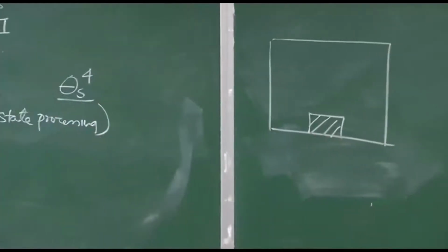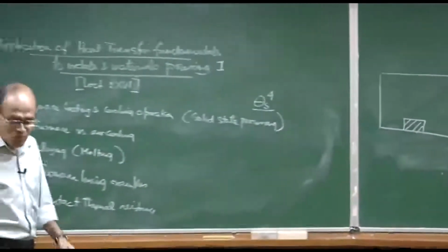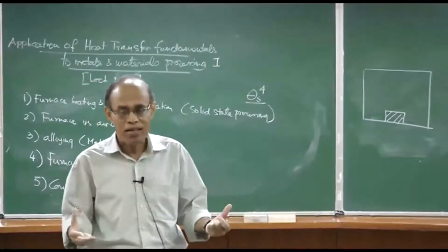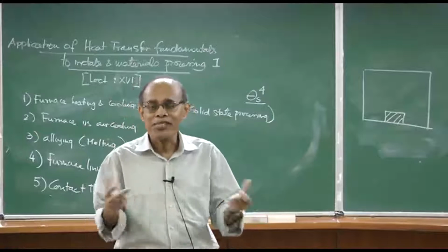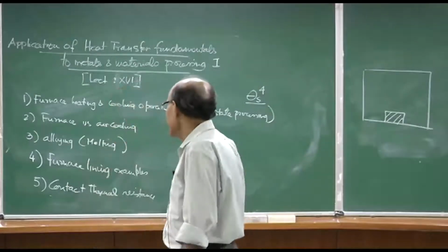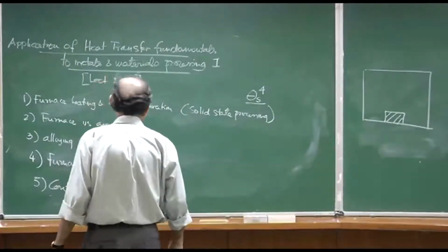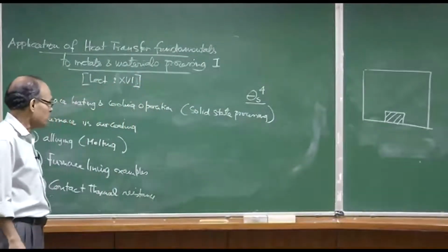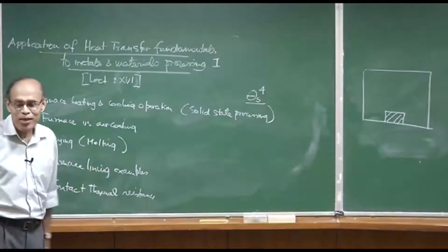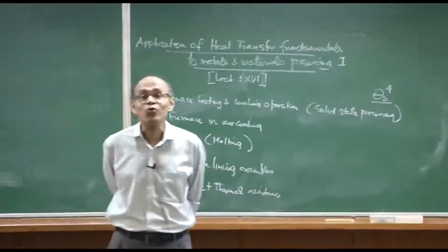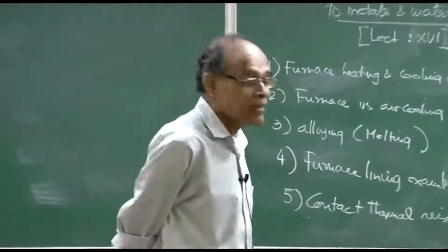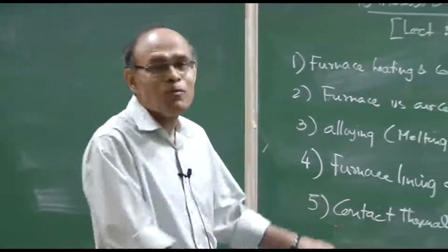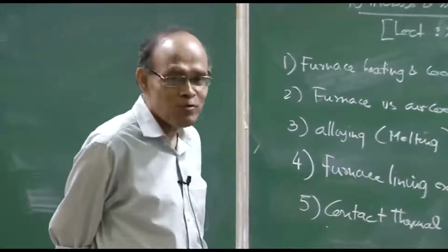Heating in a furnace, because in most cases we want to produce different kinds of products, maybe coil, maybe slab, maybe bloom, and every time we may not produce those products directly by solidification of molten metal. Some mechanical working needs to be done, and we all know that we want to do mechanical working above recrystallization temperature, because at that stage deforming the solid material becomes very easy.